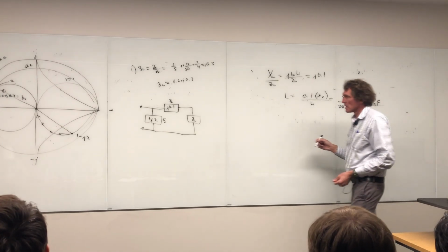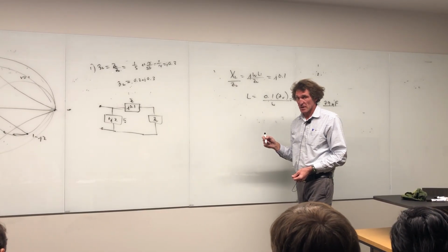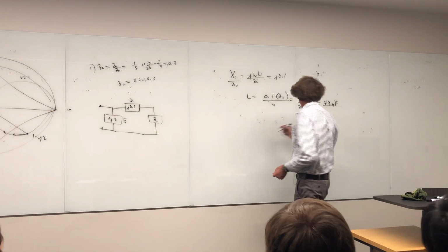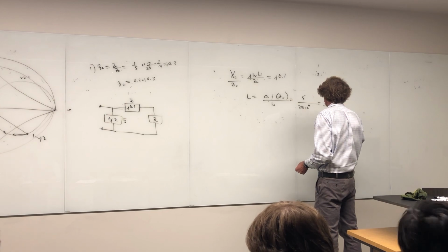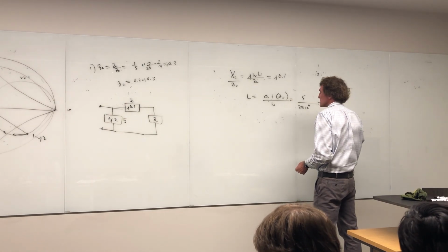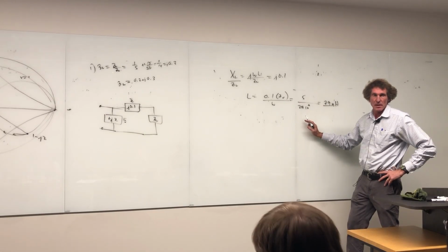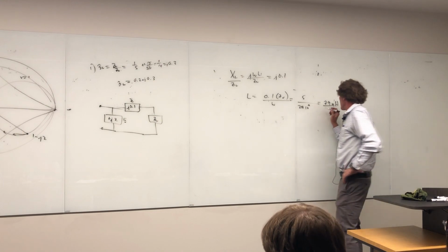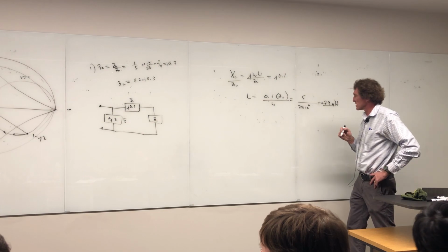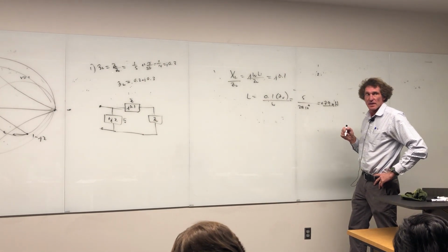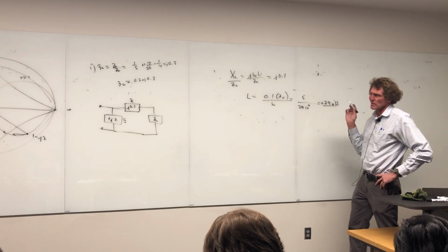Correct? Was that an inductor or a capacitor? It's in series. It is an inductor, right? Positive j. Oh, nanohenries, gosh. It should be point, yeah, 0.79. All right, 0.79 nanohenries. Check that. Yeah, that's it. 5 over 2 pi, yeah. That's about right, 0.79 nanohenries. All right, that's L1.